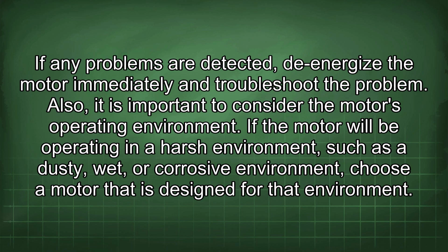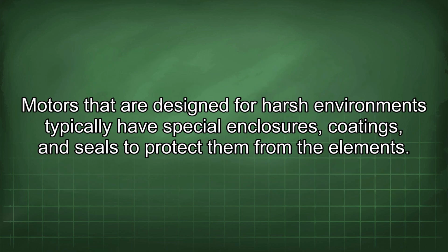Also, it is important to consider the motor's operating environment. If the motor will be operating in a harsh environment, such as a dusty, wet, or corrosive environment, choose a motor that is designed for that environment. Motors that are designed for harsh environments typically have special enclosures, coatings, and seals to protect them from the elements.